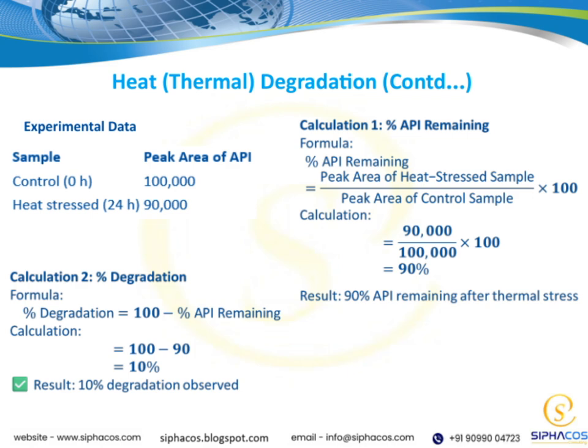Thermal degradation typically involves breaking down of the material's molecular structure when exposed to heat, and observing this process helps us determine at what point the material starts to lose its properties. This data gives us insights into the temperature thresholds and degradation patterns, which are essential for predicting the material's performance in real-world conditions. By analyzing these results, we can better tailor materials to withstand specific thermal environments, ensuring safety and